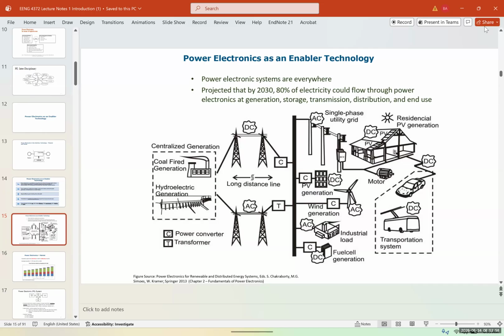The catch is that they will give you a smart thermostat and they'll give you some incentives, like they'll reduce your power bill as long as they have certain control over your thermostat. So what the power company does is during peak hours, instead of ramping up power generation, which is very expensive, sometimes they have to run a generator or something, which is very expensive, they will simply reduce the consumption. So they will put your thermostat instead of 70, 68, 69, they will put it on 71, 72 for a few hours. So they will pass the peak. So it's a two-way connection.